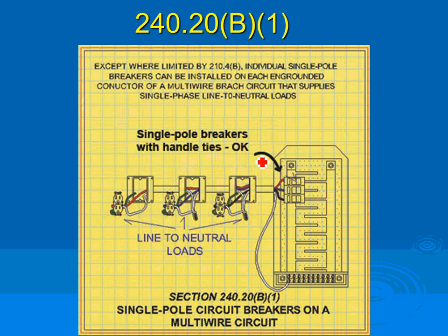And of course, if you have a multi-wire branch circuit, as we all know, if these lights here are fed from 3 different circuits, each one of them 277, let's just say they're fed from 3 single-pole circuit breakers and sharing a neutral, that's called a multi-wire branch circuit. So you have to tie the 3 circuit breakers together with an approved handle.